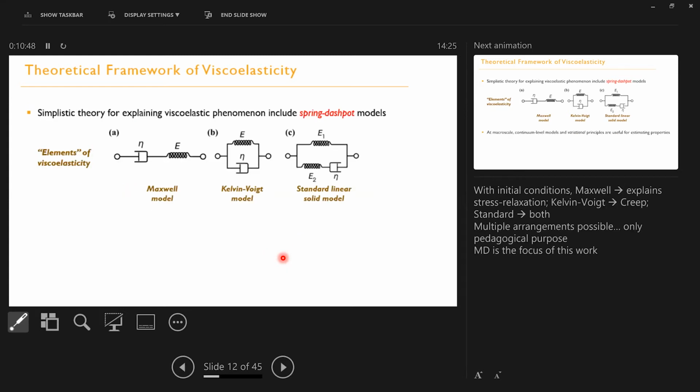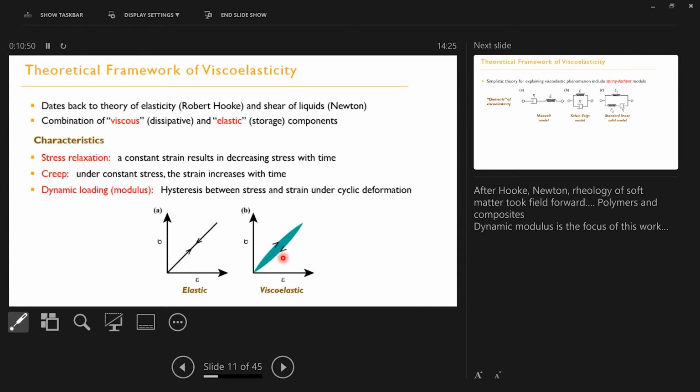For a fluid with only viscosity, what will the curve look like? There's one very important point: it depends on the rate of strain, so this is a time-dependent phenomenon. For a liquid, whenever you deform it at low frequency, let's say on the order of hertz, one deformation per second, it will be highly viscous.